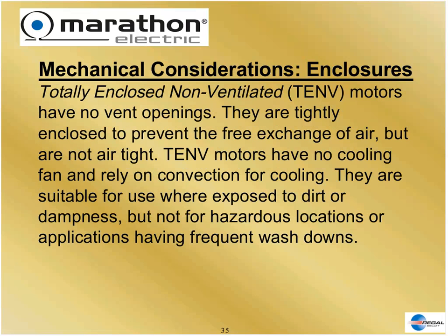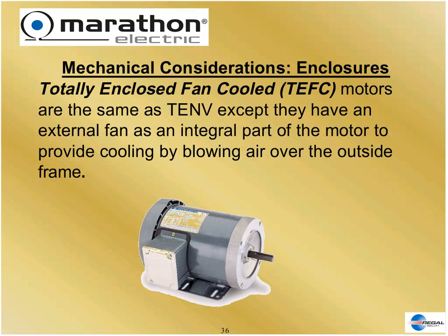So we have to sometimes make motors non-ventilated and totally enclosed. And totally enclosed motors come in a lot of varieties. First one we want to talk about is a totally enclosed non-ventilated motor. There is no ventilation whatsoever. So you can use this motor in an environment that's not conducive to go inside, but it has to be designed so that the heat will just convect from the frame. It's not anywhere near as efficient a way to cool the motor.